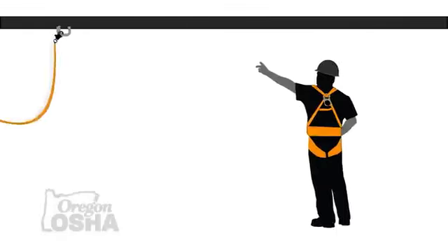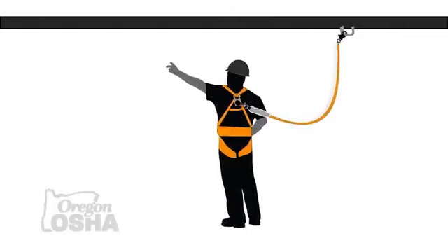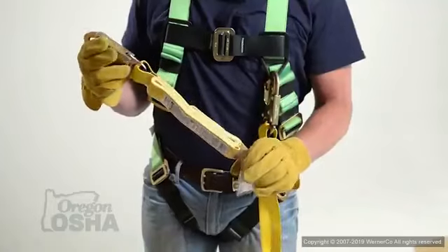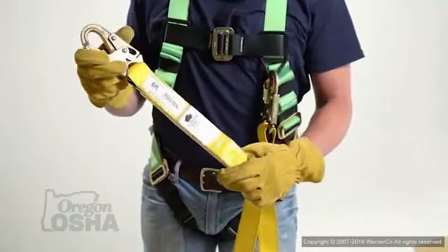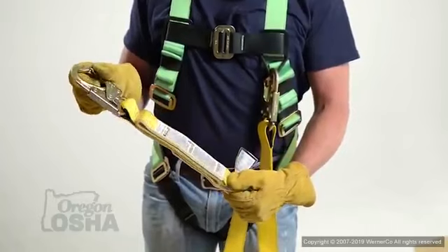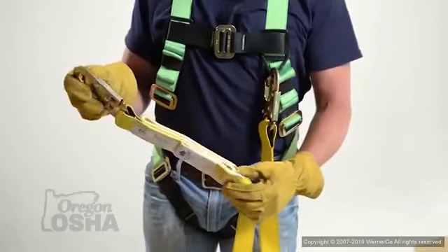When we move to fall arrest, the systems and the components that you're connected to are doing absolutely nothing for you until after you go off that edge, until after you fall. And once you fall, they should be designed so that they stop you before you can hit a lower level or the ground, and then arrest that fall and bring those forces down to an acceptable level, which is 1,800 pounds by OSHA, or an average of either 900 or 1,350 pounds by ANSI, depending on what product it is.